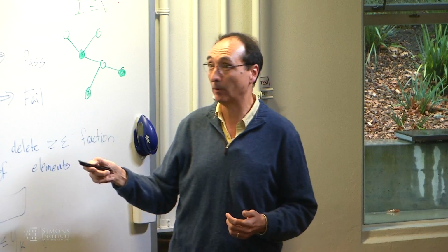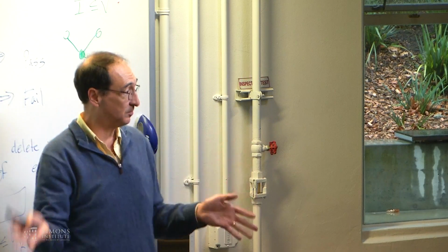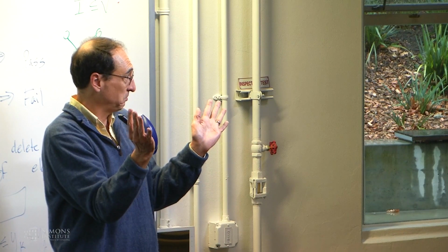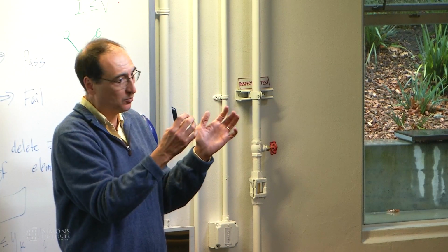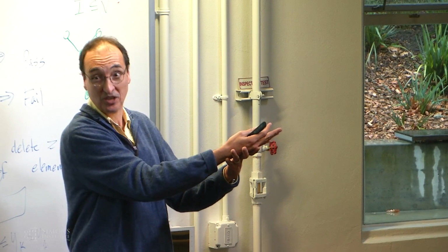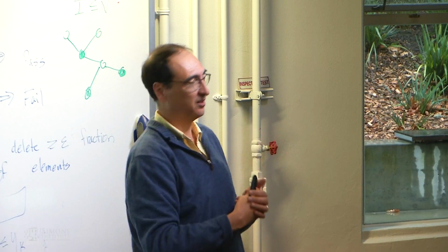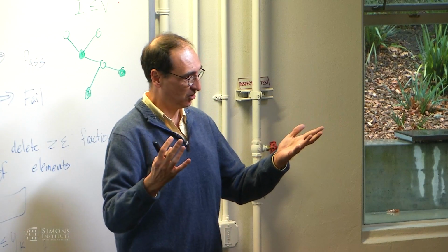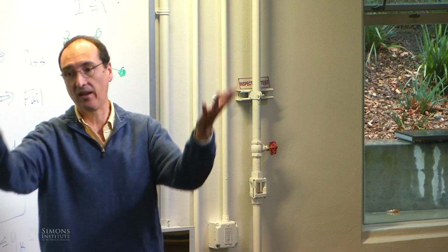So if I don't put any terminal cost here, it's like I don't care what happens after that, just minimize over the next 10 seconds. And if that means that 10.2 seconds from now you're right in front of a wall, I'll worry about that later. So that's not a good idea. You want to do something that says, by the way, you should end up at a reasonable state as well.